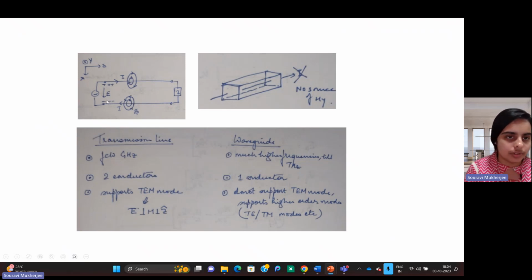And then we also know that the voltage here is not the same as the voltage that we get here. That's the basic concept of distributed circuits, that they have an effect. So the voltage can attenuate depending on whether it's lossy or not. Otherwise, there can be phase accumulation that can come in. So the voltage here is not the same as the voltage here.